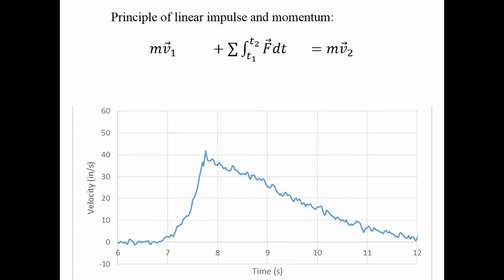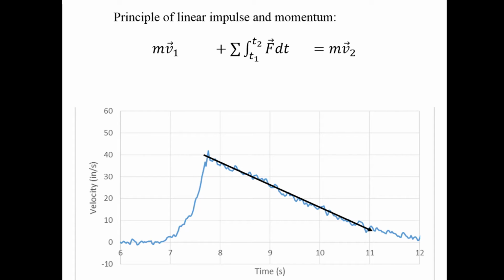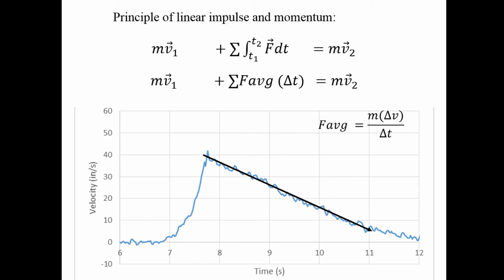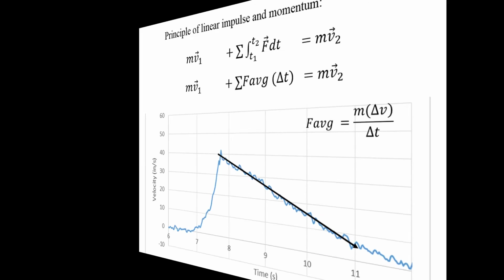We can clearly see the effect of rolling resistance when we look again at the velocity graph. The rolling resistance continues to apply its impulse after our applied force ends. Let's use the impulse momentum equation to actually estimate that rolling resistance force. Now, rather than predicting velocity by applying a known force like we did before, we will rearrange the average impulse equation and estimate the force by measuring the change in velocity.